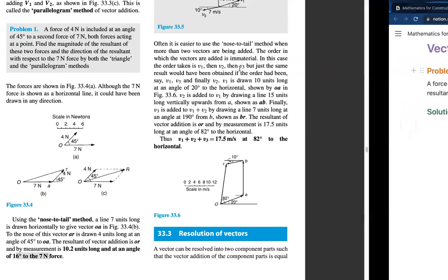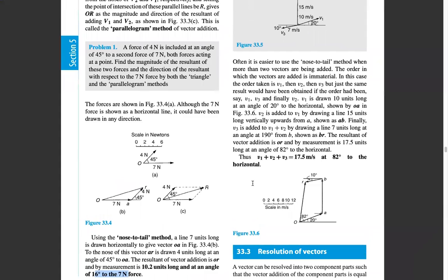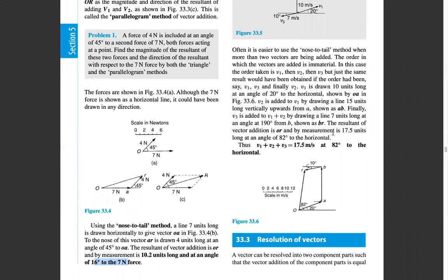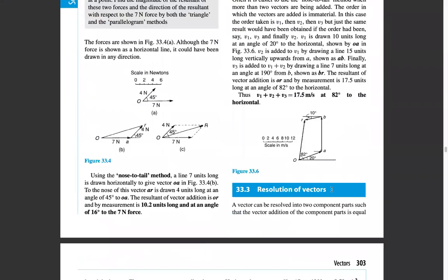Here in this question, we didn't have anything like north, south, east or west. Similarly, here you have several forces acting together. You could use vector addition to represent it as a polygon, because now you have more forces. Before you had 2, so you resulted in a triangle, but here you have 3, so you end up with a polygon, and you have to add this using geometry, triangles. So it gets a little bit tougher the more forces you have acting at a point.